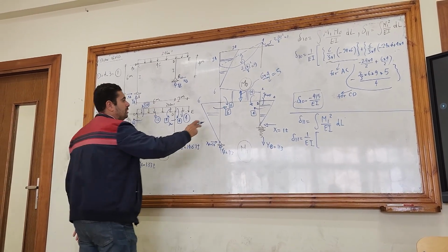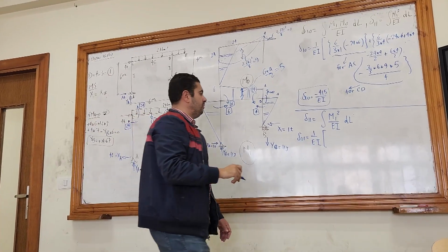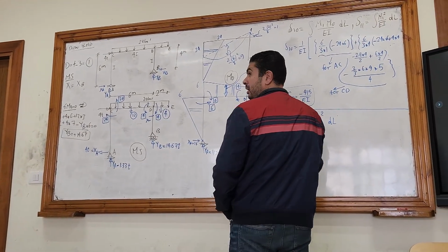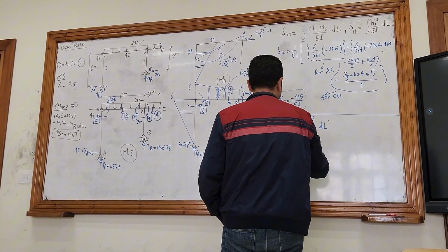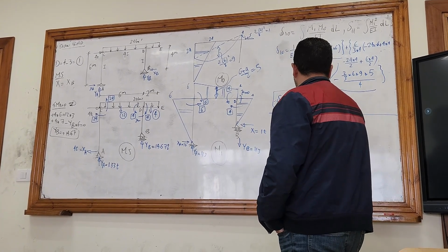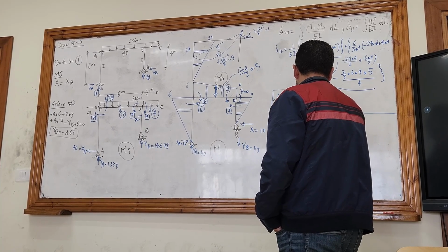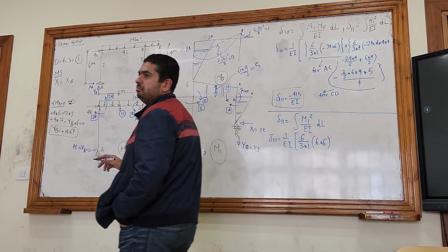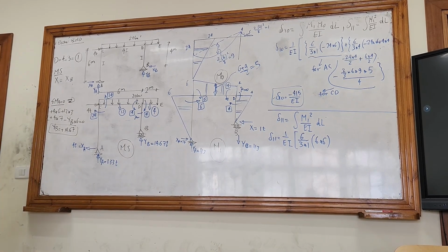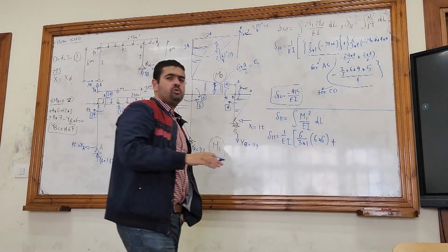The first term, it's a triangle with itself, right? A triangle with itself. L, 6, divided by 3 multiplied by the I factor, which is 1. And then the first value, so it's 6 times 6. And no signs, no negatives, okay? 6 times 6, and that's it. Plus, it's always plus.